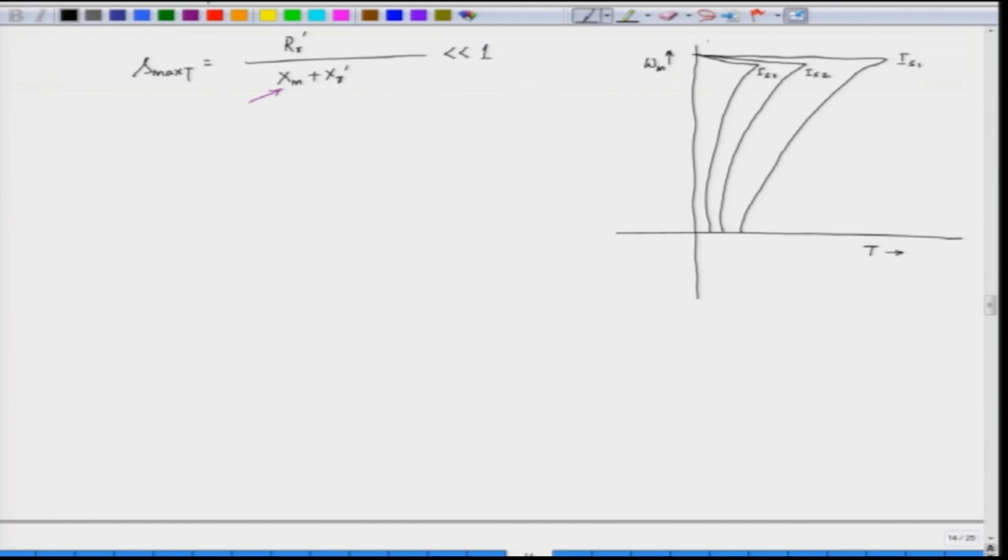of course is the synchronous speed which is omega ms, the origin, and we have the torque speed characteristic, and this slip for which we get the rated torque is very small. So, this is the operating slip. Let us say we operate corresponding to IS1, this value of slip, this is the speed here. So, slip will be of the order of something like 0.001, which is a very small value. This is the slip for the rated torque.